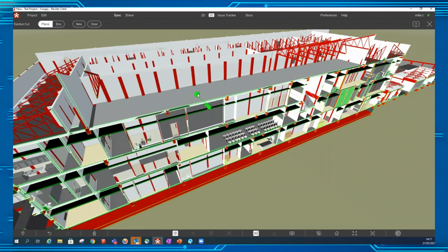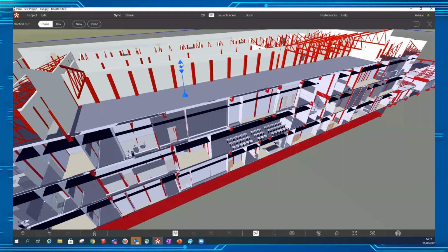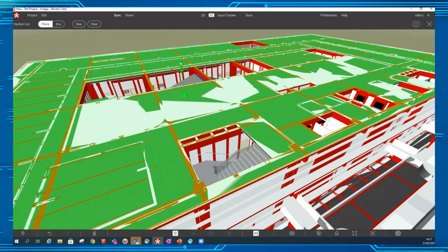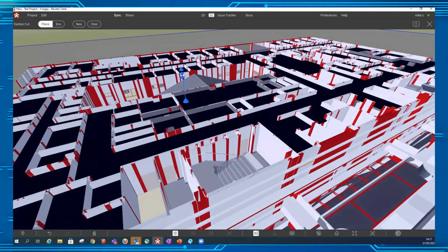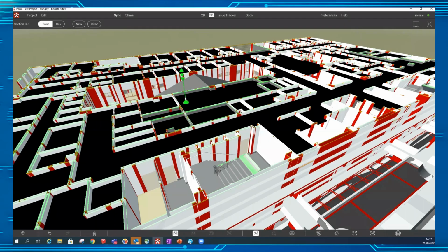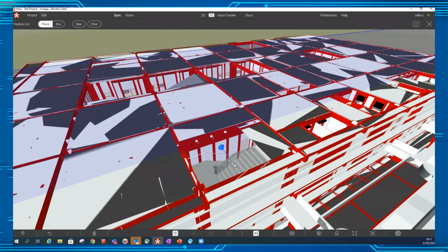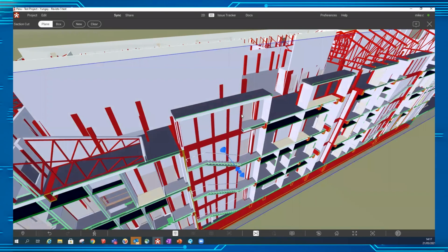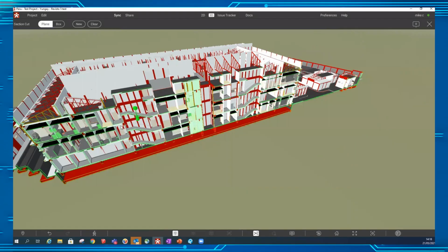Okay, and if I wanted a section looking down, then I could again click on this end and stick it to a horizontal surface, and then by using this end, I can pull that up and down. So for the purposes at the moment, I'm going to create a vertical sort of slice through the building.